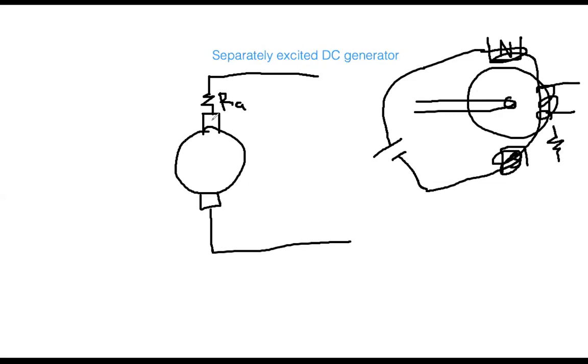Remember I was telling you that a DC generator produces AC, and that AC is converted into DC with the help of the commutator. After the commutator, there are carbon brushes, from where the output is actually taken. That's why, in the book, you will see these two symbols, typically fully colored. These are called the carbon brushes.